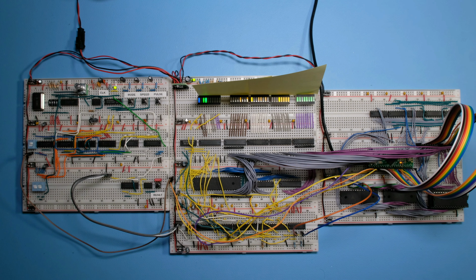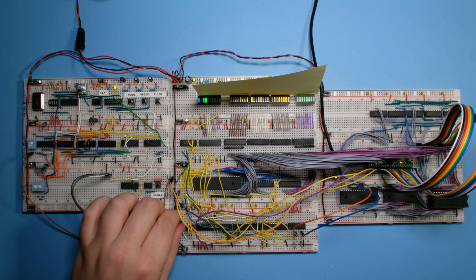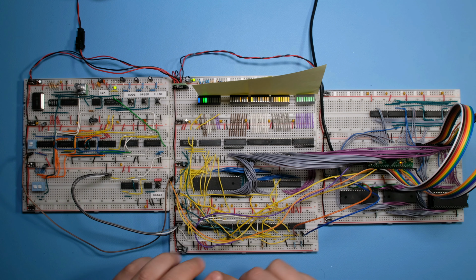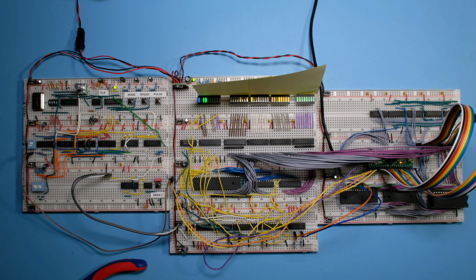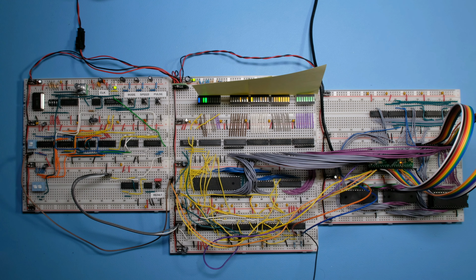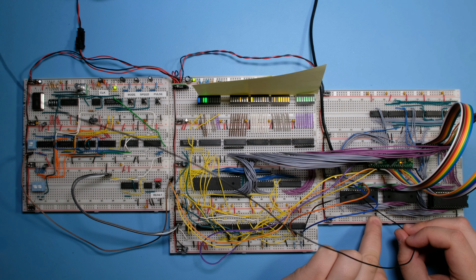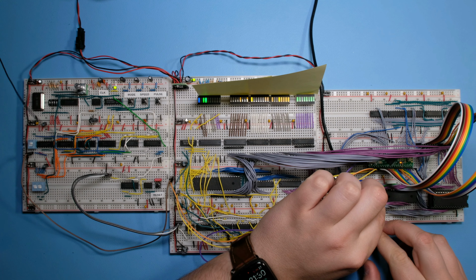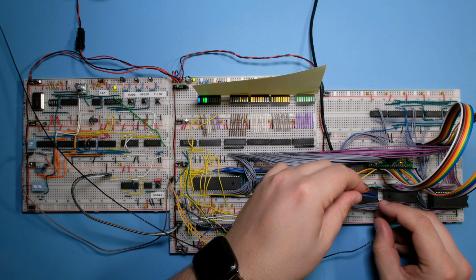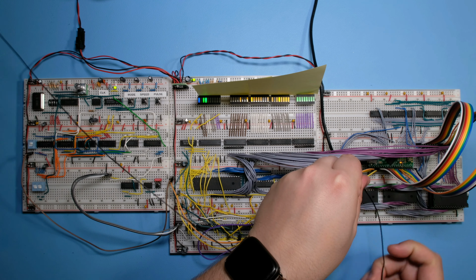So I already added a ground wire next to the clock here in the last video. I'm going to do something similar for all the inter-breadboard connections here. The read and write pulses are driven by this chip, which is grounded here. So we need to take a ground from here and bring it with them to here. And this chip is grounded here, so we're gonna have the wire go to here. And of course it needs to go close to the signal wires.